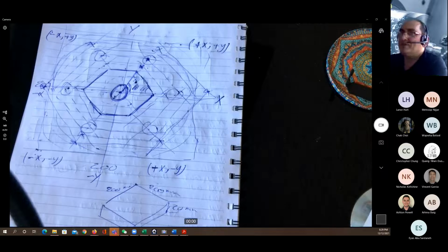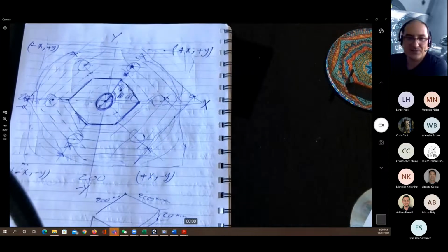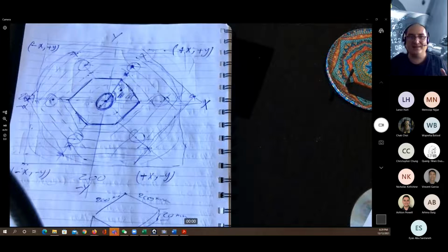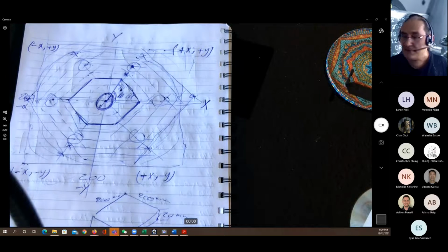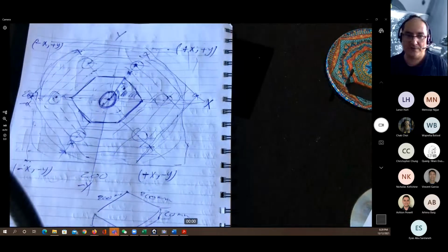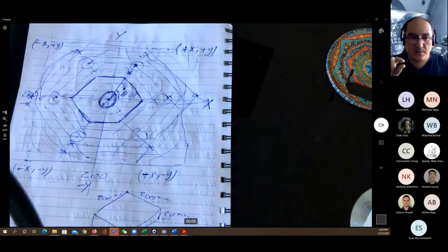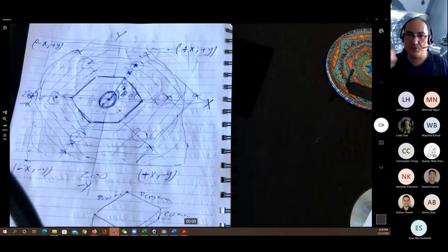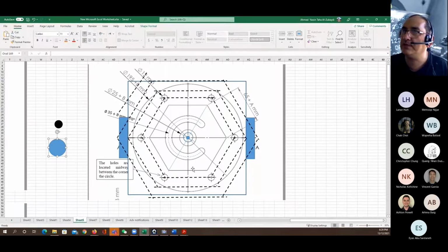Okay. So it's a straight line. That means what we are going to do is just go to one of the points and start to write down G01, G01, G01, X, Y is going to be changed. That's it. So I'm going to write down my first line, my first code, which is going to remove a layer that's equal to 2 millimeter thickness and to remove the material around the hexagonal shape. This will be my first code.